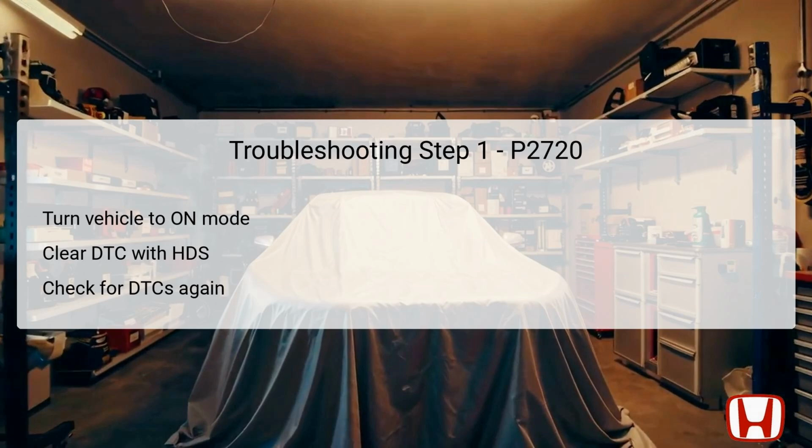If the DTC reappears, it indicates a persistent issue within the solenoid circuit that warrants further investigation. If the code does not show up again, it might indicate an intermittent failure requiring attention to electrical connections and possible repairs.